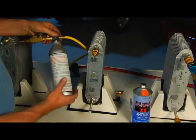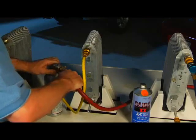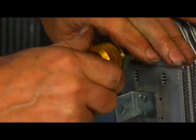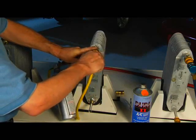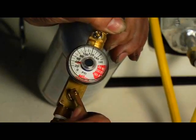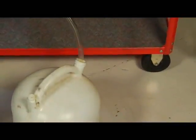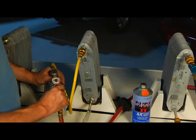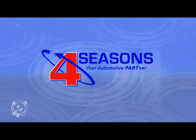By adding a regulator and an air hose nipple to the flush bottle, we can attach a shop air hose and regulate the air pressure to the bottle. Instead of using the spray nozzle, we'll use one of our component adapters and attach the solvent hose to the adapter. We can now force the solvent through the evaporator at a consistent 40 psi. After all of the solvent has been expelled from the flush bottle, you can adjust the regulator to 80 psi without ever allowing airflow through the evaporator to cease. This is the most effective way of preventing the solvent or dirty oil from pooling in the evaporator.